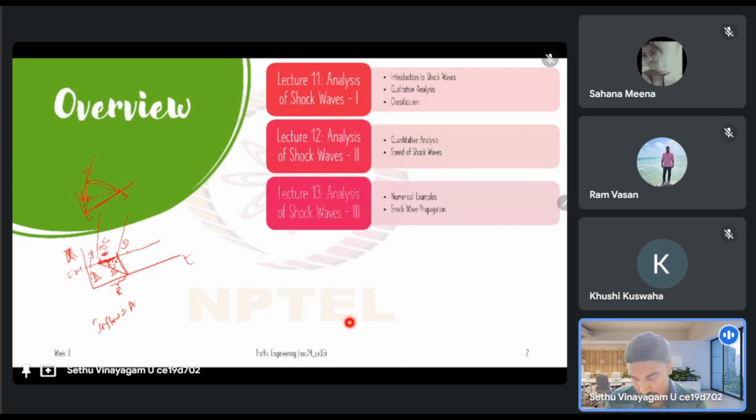So once these two shock waves meet, that's where all your queue will be cleared, and whatever comes afterwards can again pass through without any interruption, right? So that's how the shock waves will help us understand the propagation of traffic state. This is one particular example of a signalized intersection, but it can be used to understand any such scenarios where we have congestion or bottlenecks present in the field.